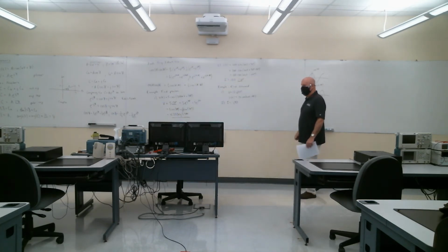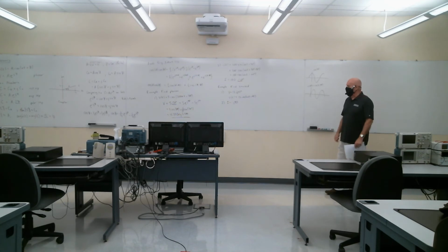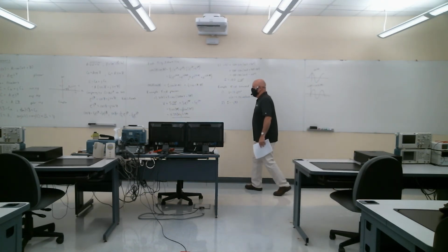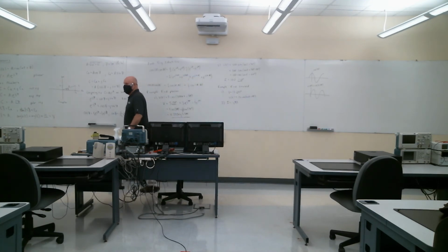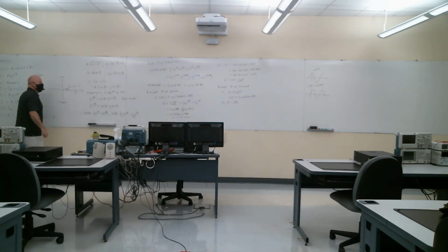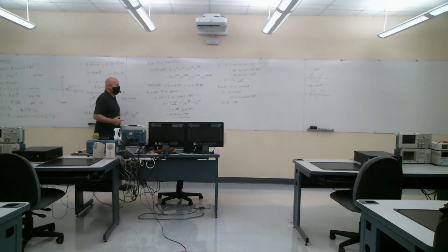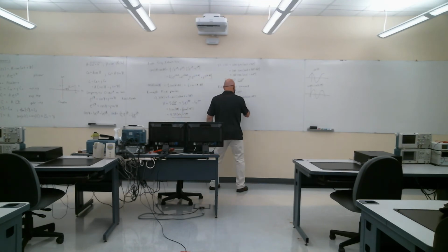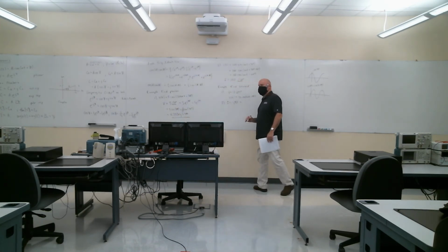Now that's a puzzling one. I is minus j90. That's really in rectangular form with no real part, right? Where would that point be here in the complex plane? Straight down, it would be here, 90 units down, right? How would we express that in polar form?